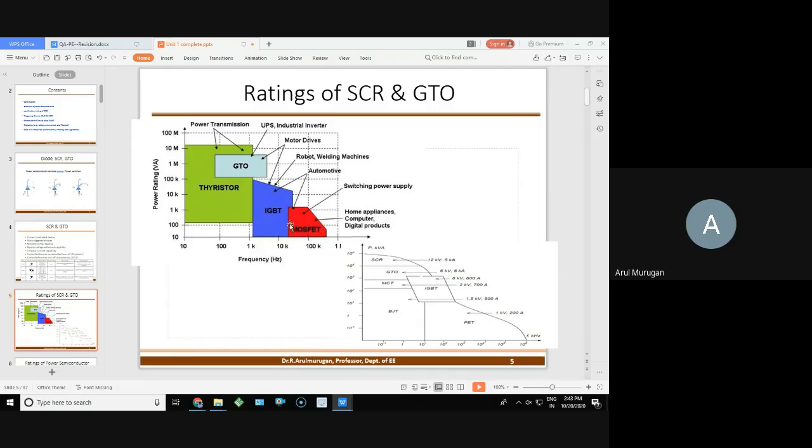So that's why in most inverter applications you have seen, IGBT is used everywhere. Chopper applications, inverter type applications, everywhere they are using it. Where is SCR used today? SCR is used for rectifier applications as well as transmission lines. In a transmission line, high power devices are needed, so SCR or GTO is used there. But these are unidirectional only.